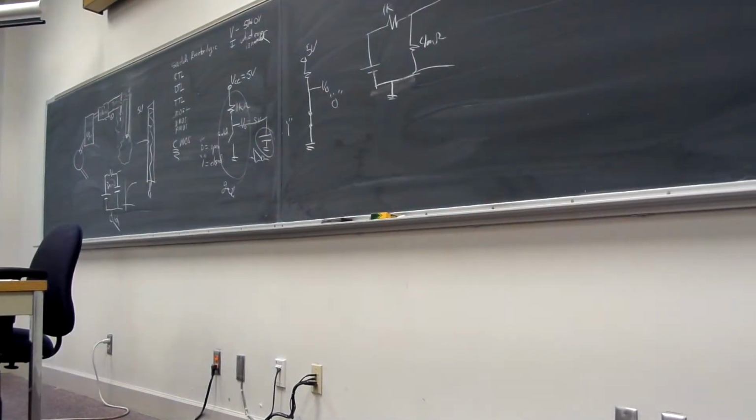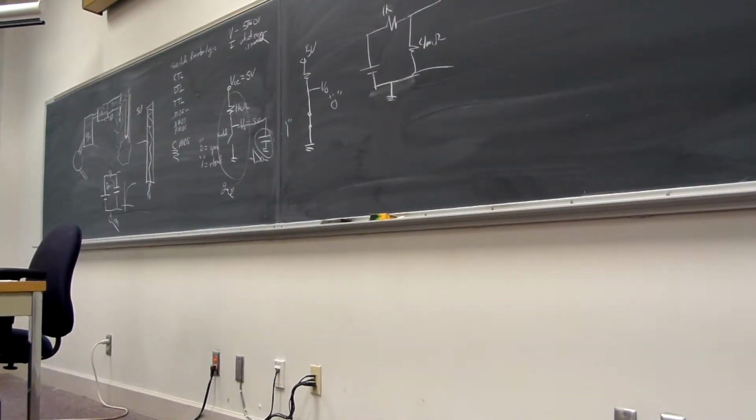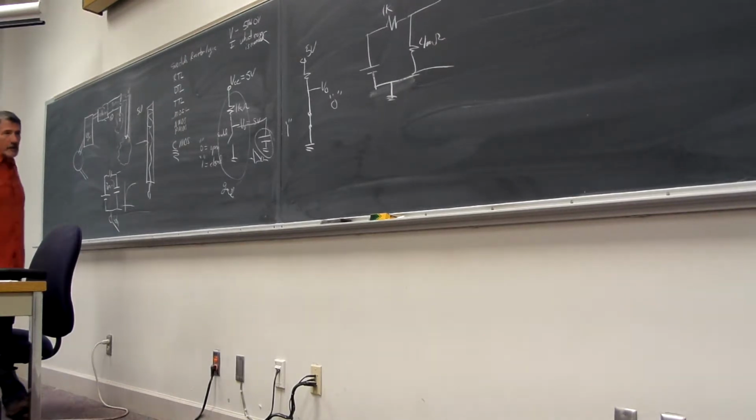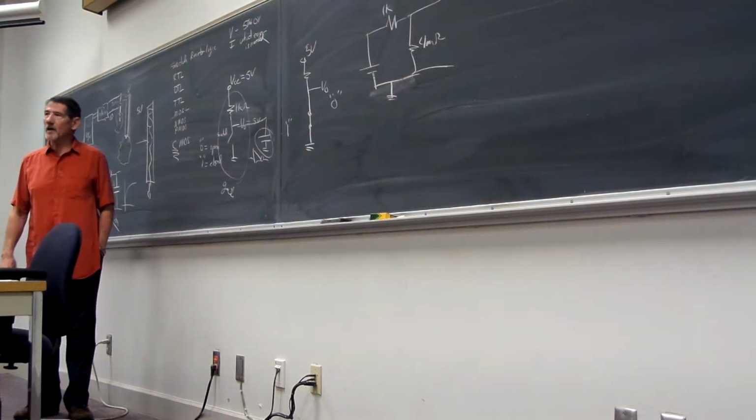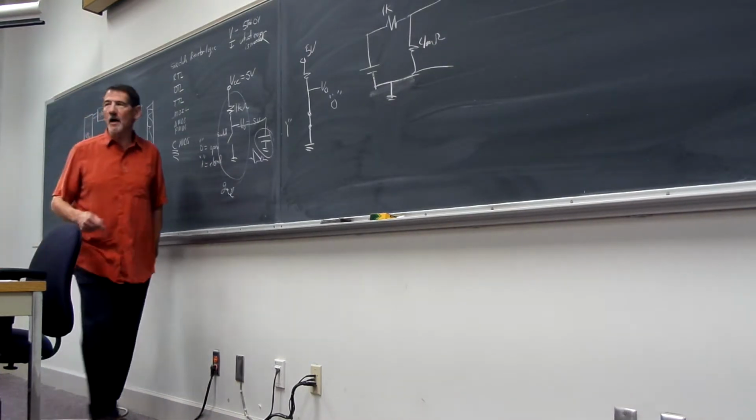So you start jacking up that resistor value and now what? It slows the gate down. Can't stress this enough. Anytime in design, you try to fix one parameter, you're squeezing it, something pops out someplace else. Okay, so design is always about trade-offs. Doing okay? All right, so having a switch there, while it sounds good, it's not very good.